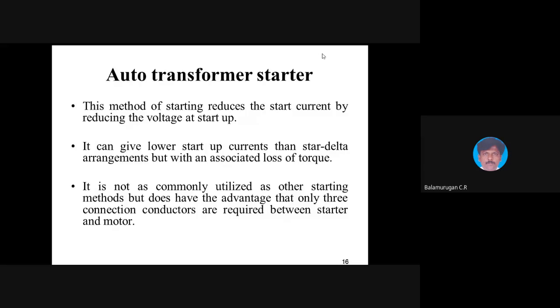So on the stator side, we are going to connect three resistances in series, for the R, Y, B phases. You can connect a three-phase rheostat, or three-phase resistance, in series with the stator. And there is no external input given to the rotor circuit. You are not supposed to connect anything on the rotor side. So in the stator, we are connecting the resistance in series with the stator winding, R, Y, B.